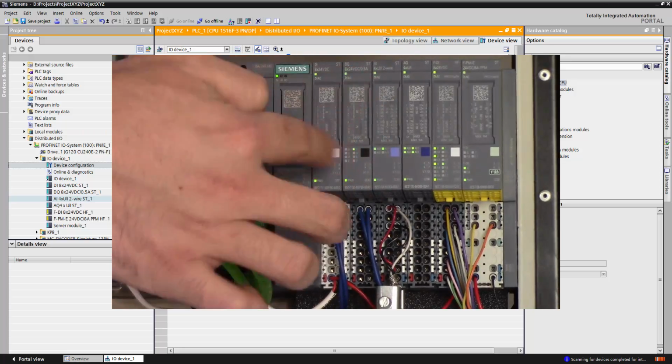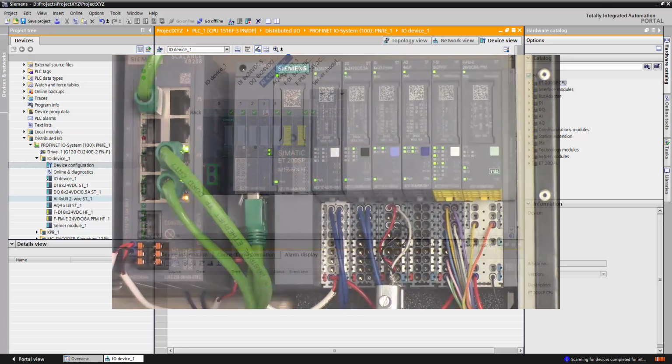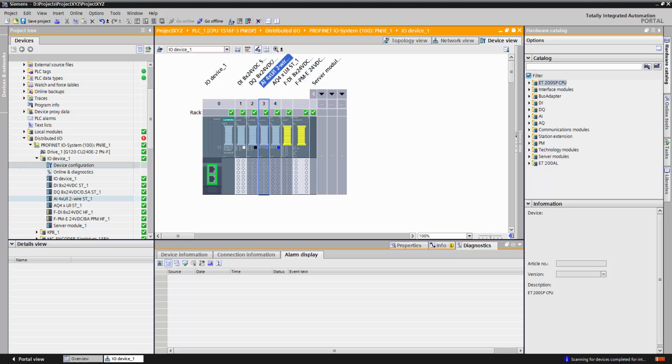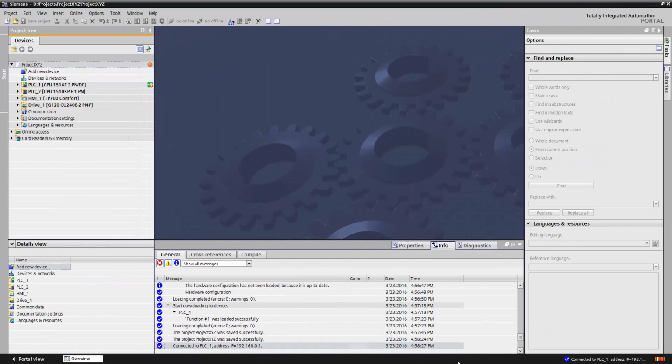When I plug it in, I fix the problem and notice my error light goes away. Along with the hardware light clearing, you can also see that everything gets cleared in TIA Portal and I am error free again. In this next example, I created another kind of problem. Notice I got the orange exclamation point, meaning that this is a software problem.